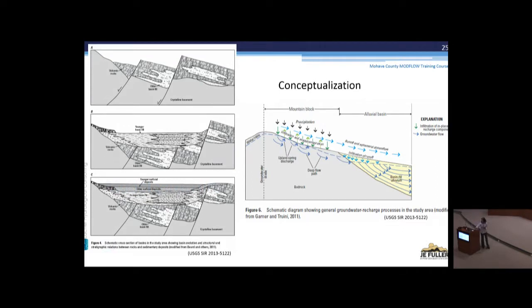These graphics are also from the USGS report on the preliminary model for this basin, and this describes the general geologic features in this area, not just in the Hualapai Basin, but the neighboring basins. So it basically goes like this. Initially, there were some extension faults going on, the basin range expansion, which caused blocks to drop down, so this side dropped down, this side moved up, this side dropped down relative to this side. Anyway, it's basically stretching apart.